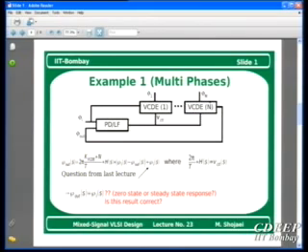Now this delay changes in such a way that, for example, I had lagging, right? Now it will try to reduce VCTL. Suppose the slope is negative, okay? So this will increase VCTL, delay will reduce, and therefore now it will try to reduce the phase. So what would I expect? I would expect VCTL to increase, VCTL to go to negative values, and after several rounds, it should come back to 0.